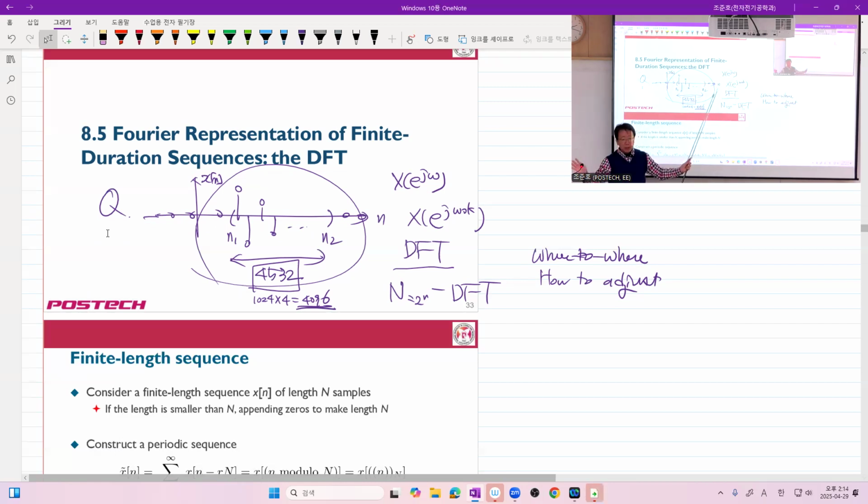Now, we take the possibly non-zero part only from this signal with a lot of zeros. Of course, there are many ways to take them. As I told you, you may take exactly the non-zero entries only, or you may include some zeros preceding or following the interval. Our textbook and I also emphasize how we handle this so-called zero padding, when we put something here or there.